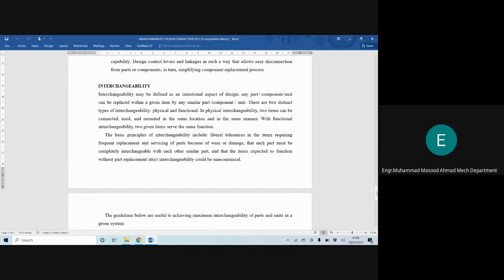So that is very important and interesting. When you are going for interchangeability, then you have to define certain tolerances. The parts which you are selling into the market as interchangeable parts, all of them should be usable. But as there are tolerances, you have to reject some parts as well.